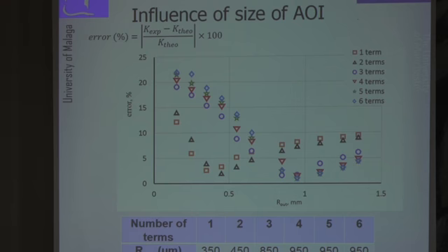We can see that, of course, the bigger the area of interest is, the more terms in the Williams equations we will need, and that is shown approximately in this plot. These orange squares show the evolution for estimating with one term in the Williams equation, and in black we have two terms and so on. The minimum would be the best prediction by the model.